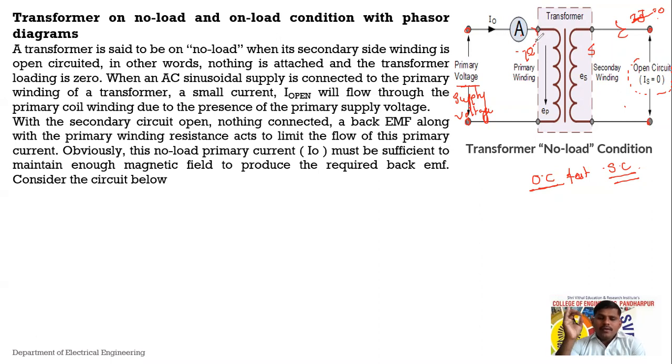No, sir. Do you know that in case of motor or generator, we have discussed regarding losses. One we can call a constant loss, one we can call a variable loss. Variable loss in the sense it will depend upon the value of current, that is load current. And constant losses depend upon manufacturing parameters, that is the magnetic property. So there is no load, so variable losses should not be present.